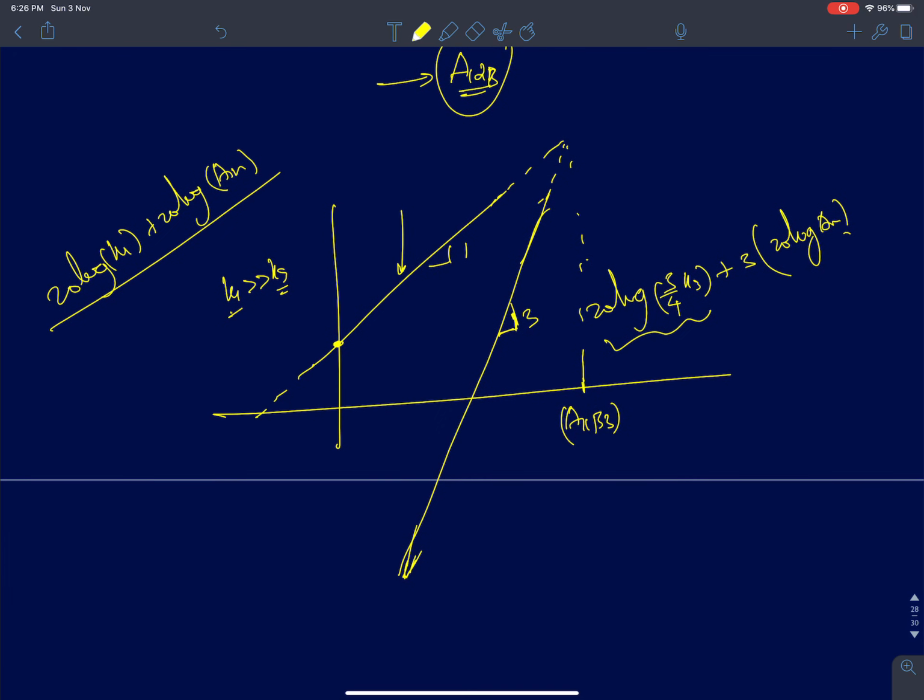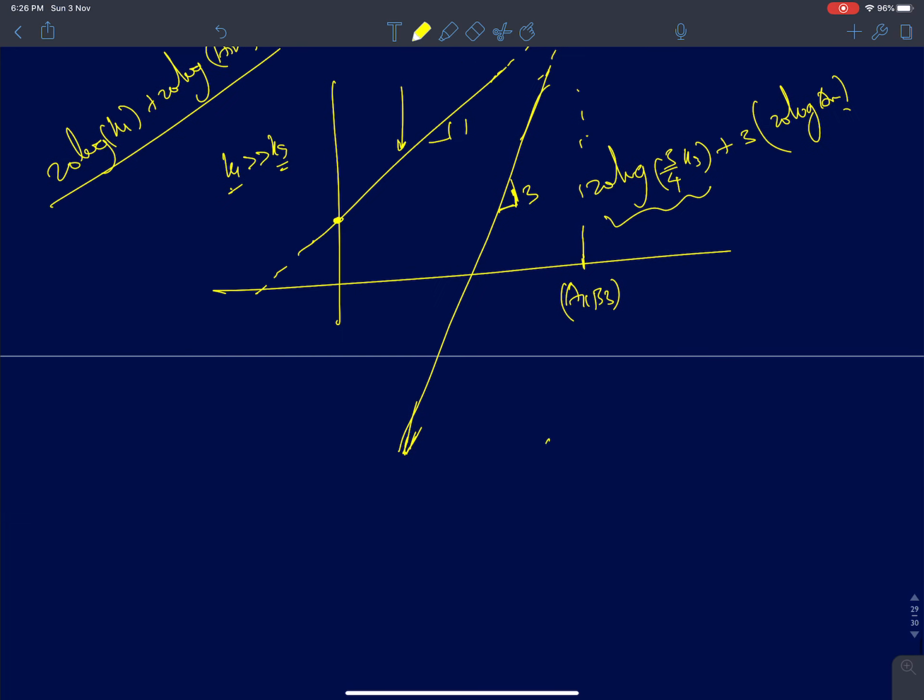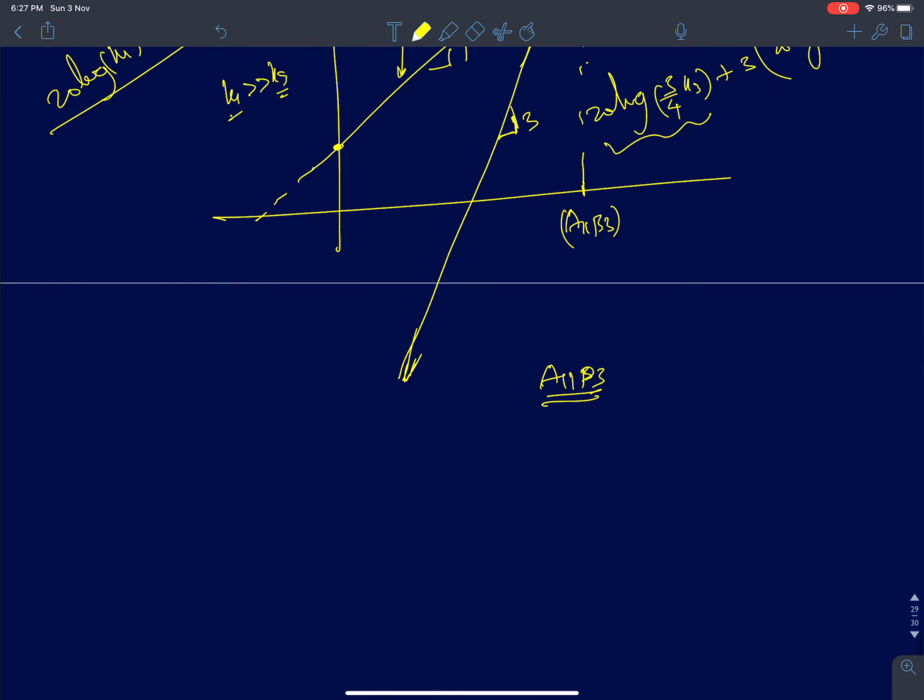So this is what we discussed in today's lecture about the effect of nonlinearity, especially in RF systems. IIP3 is a very useful metric because it is mainly applicable for RF systems, which are narrowband. Normally in low frequency circuits, you don't really care, because if your bandwidth is very small, harmonics are going to fall way out of the bandwidth, so it shouldn't matter. But in an RF system, it's very common that you will have two interferers which are very close by, and they can create an unwanted component at the center of your desired channel itself.